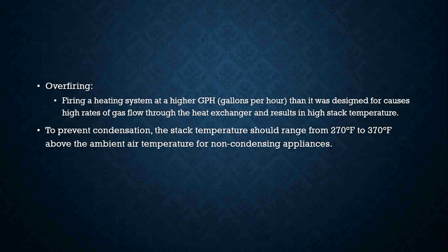Overfiring a furnace is going to cause high stack temperatures. Okay? Firing the heating system at a higher GPH than it was designed for causes high rates of gas flow through the heat exchanger and results in high stack temperature.